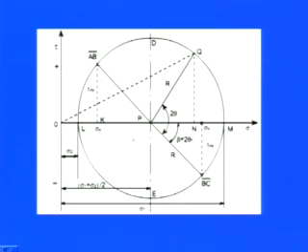So you see here, once we have AB bar, once we have the BC bar, you have sigma 1, sigma 2, you have sigma x, you have sigma y, and you have tau xy. So what exactly the relation is, it's pretty easy to find out. And if you are saying that now it is rotating where the maximum shear stresses are, so again you can rotate by 2 theta s, and you can get the value of the PQ.